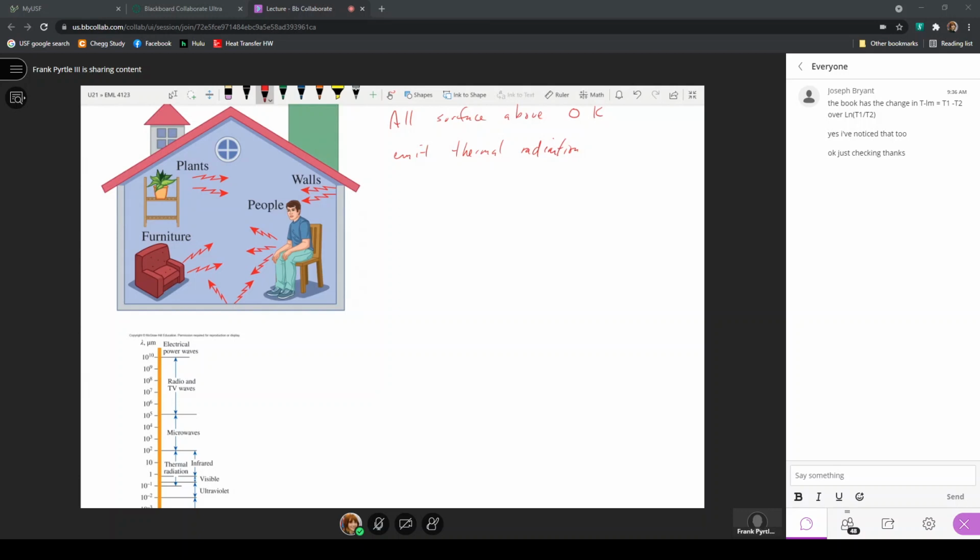When you touch vinyl compared to when you touch the fabric, the thermal conductivities are very different, and so the temperature gradients into your hand are different, which, when multiplied by the thermal conductivity of your skin, give you a heat flux. So your skin can assess differences in heat fluxes much better than it can temperatures.